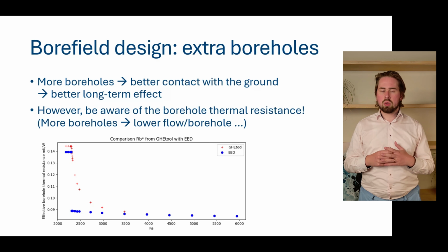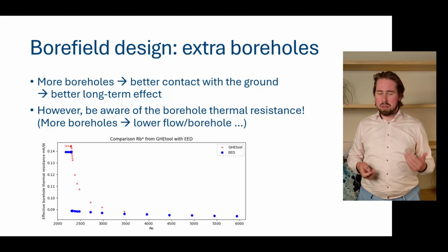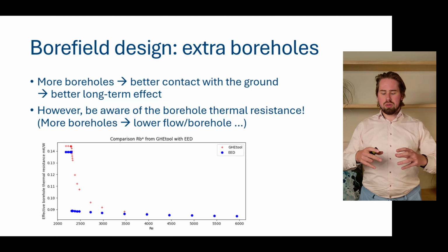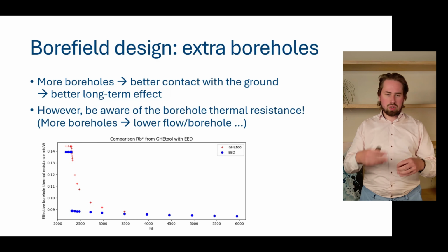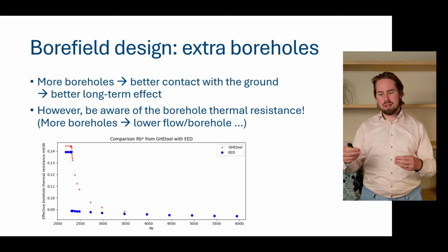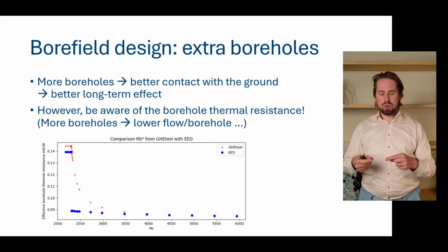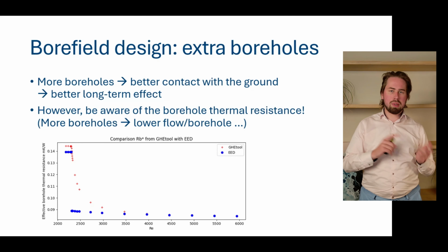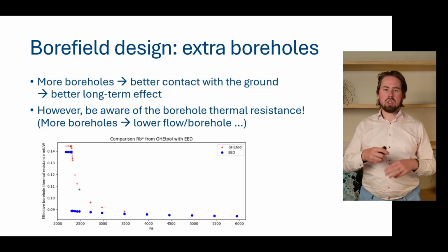So yes, drilling extra boreholes is typically a good idea, but you need to make sure that your borehole resistance does not increase too much, because then we don't have a good heat transfer, and the imbalance becomes even worse. In fact, it's even possible, and perhaps it's a good exercise for you, to create this situation where you say, okay, let's add another borehole, and due to this fact alone, this extra borehole does not change the temperature in the end, because we just go from coping better with the imbalance from a long-term perspective to having a worse borehole resistance, compensating for that improvement. So this is something to really think about when you're just adding extra boreholes.